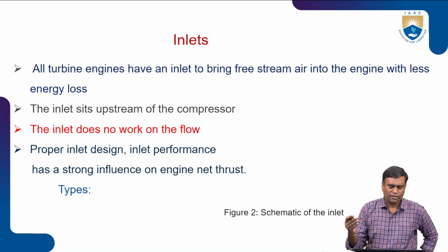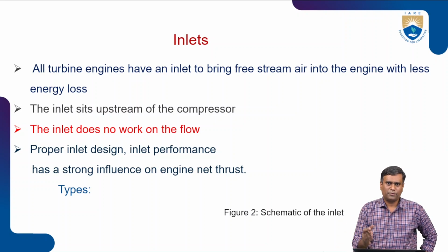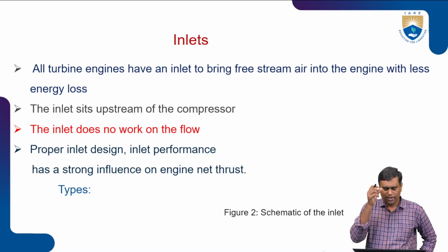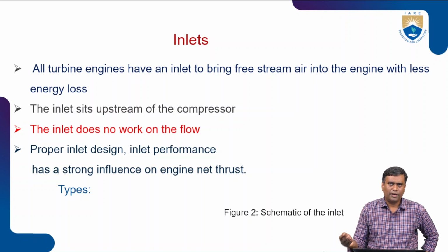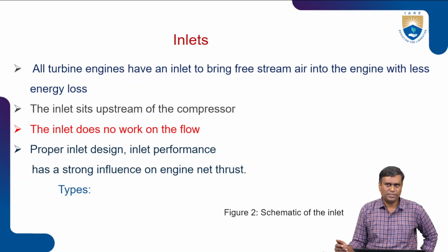And the position of the inlet is just before the compressor. Of course, it is the initial part among all these components. This is the first part, and inlets don't do any work on the flow, and proper inlet design and inlet performance have a strong influence on engine net thrust.